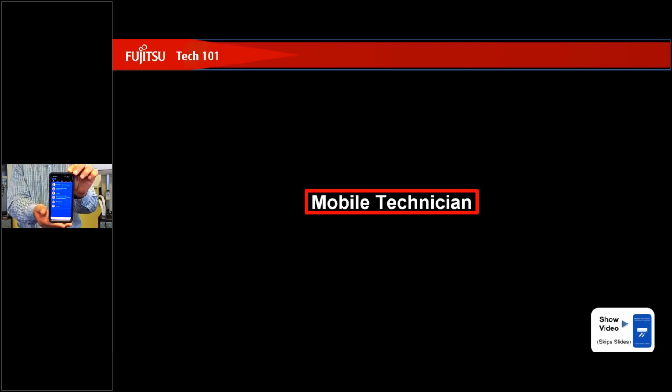Yeah. So when I hit the toolbox, I can click on thermistor, any pressure switches, a PT chart. I can go there and use this to find any values if I need to ohm out any thermistors. We have thermistors all over our equipment. This is how we gather information and bring it into the IPM module so it can figure out how to pulse the DC to the different components on our equipment, which cause an effect, which change a temperature or a fan speed. So if I'm looking for any value, I'm going to find that on a thermistor.